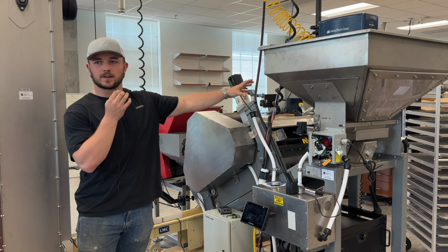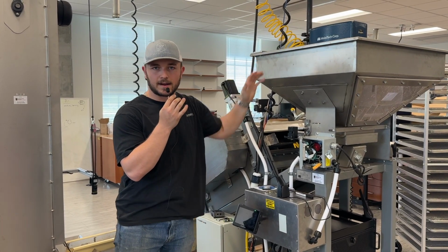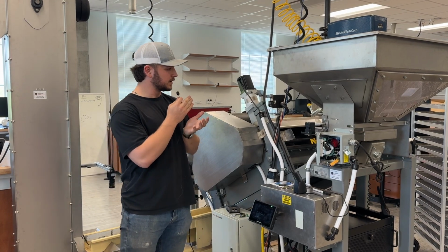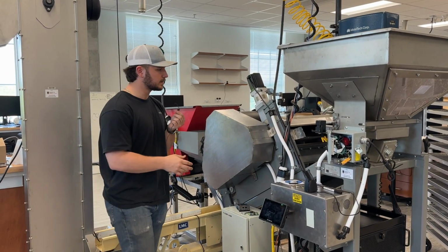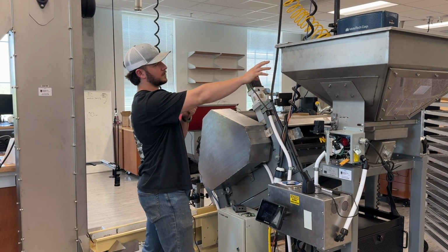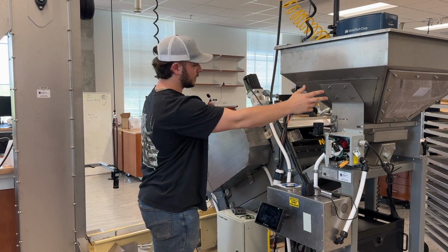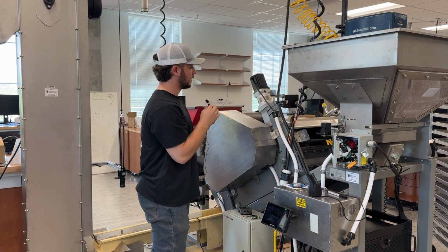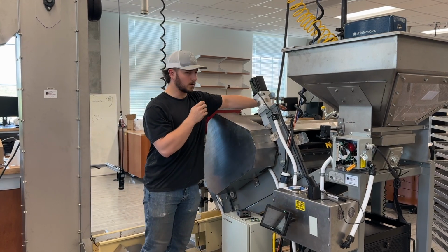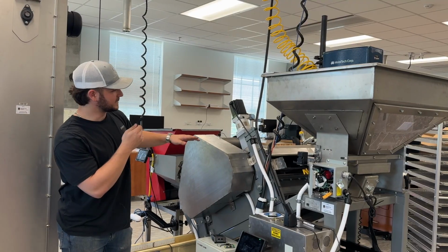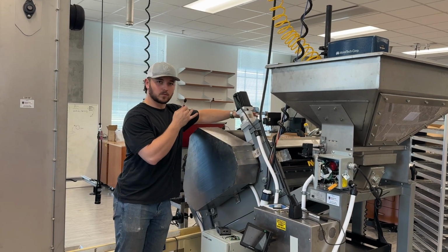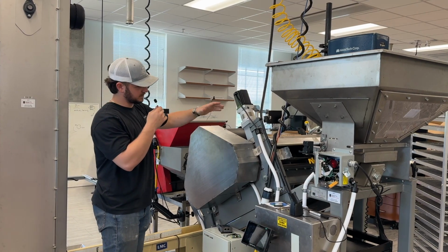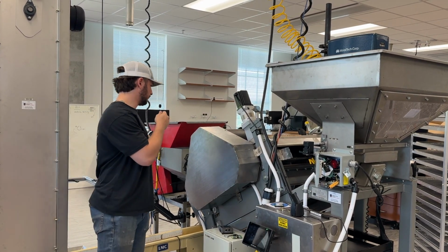After they air dry for some time, we then move and put them into the cracker. This cracker here is the JC cracker. It cracks pecans radially, so along, I guess, what you'd call their sides. This is our high throughput piece of equipment here. It takes pecans in this hopper, moves them along this vibratory conveyor here, and then drops them off in large numbers through this machine, where it has plates here that are essentially the width and length of the machine that are impacting the large batches of pecans as they flow through here.